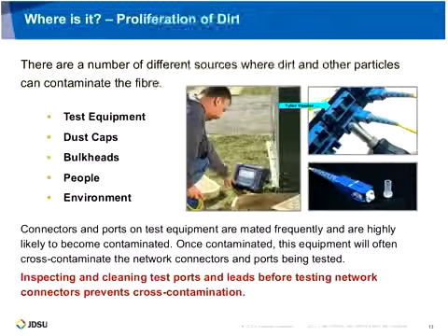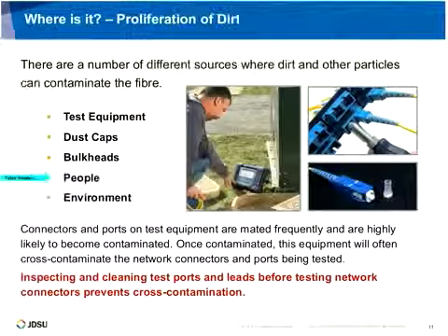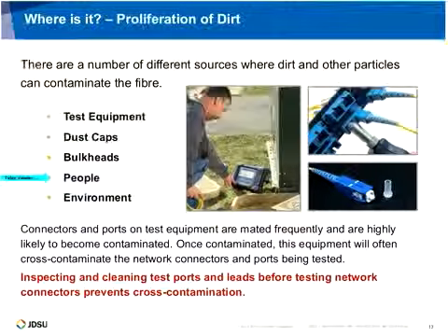The next one sort of goes without saying, but people are a big source of contamination. If you've ever handled these connectors and accidentally touched the interface of one and then looked at it through a microscope, you know what I'm talking about. You see firsthand just how easily a fiber interface can be contaminated just by accidentally touching it with your hand.